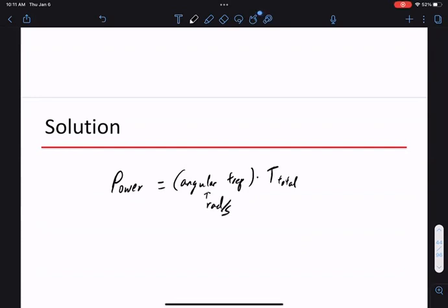So we need to convert our frequency, which is most times in RPM, to radians per second. It's very natural to talk about one blade frequency in RPM. They typically rotate at 30 RPM, or 50 RPM. But in calculations, we need this to be in radians per second.